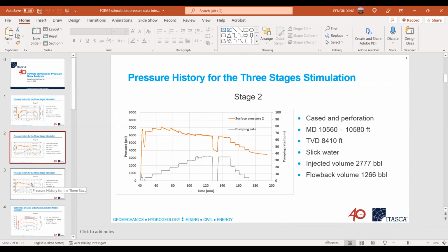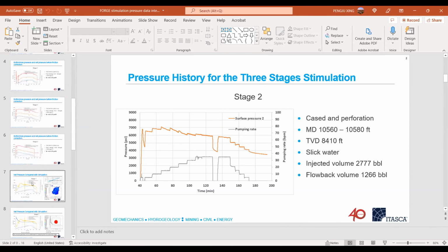So that's why net pressure matching is not very common in horizontal wells like in shale, for this reason: they've got this extra issue kind of throwing a monkey wrench in it. So that's what it looks like to me, is just you've got a lot of tortuosity initially, and as the fracturing develops, that tortuosity erodes. So I wouldn't interpret that as a net pressure trend. I would just interpret that as a near wellbore tortuosity phenomenon. And so you did a step down at the end of the test, it could help understand the tortuosity at the end of the test. But if you had done a step down after 10 minutes of injection, you might have seen something totally different. And so that was my comment.